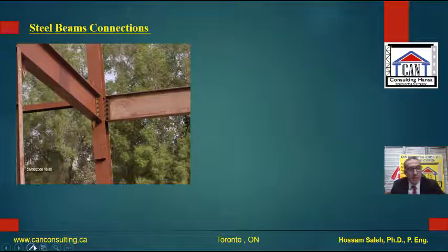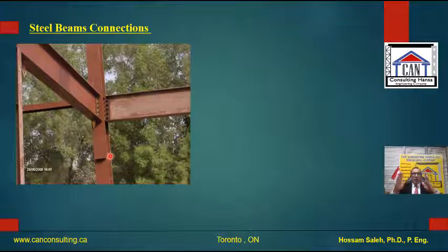And here, if you have a steel beam, the steel column is straight. When you deliver the steel column to the site, it should be as long as possible. So you can have 3 floors height or 4 floors, and normally you can have around 50 feet.